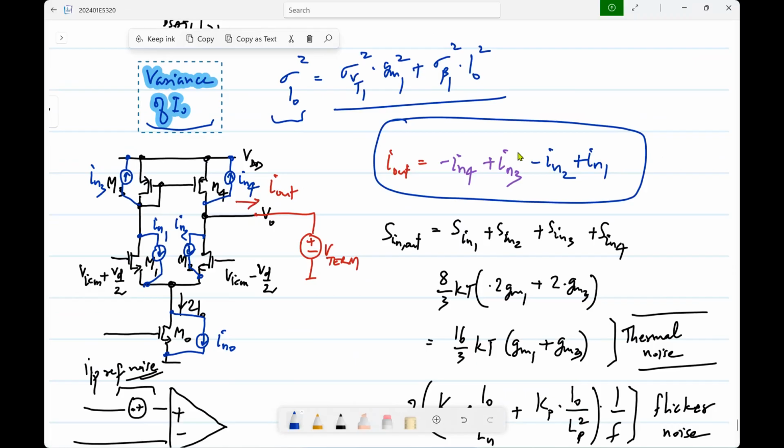No, no. The sum has to be the same. Then you can vary them any which way you want. No, no, it won't, right? Because the op-amp reacts to the voltage here. The actual voltage is something. The relationship between the actual voltage and the input across these terminals is defined by that. Whether you put it here or there or both, it doesn't really matter.